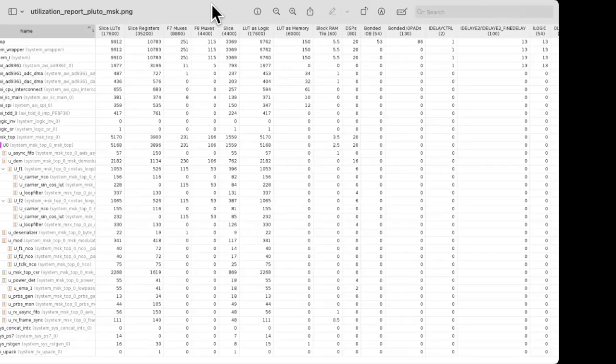Two weeks ago, we talked about refactoring this, because in development you need access to registers. You need to look at everything. Everything gets a 32-bit counter or a register. So about half of the MSK top is in the configuration status register. This is never going to go to zero, because you absolutely have to have register access to be able to configure your modem and get status of what's going on with it.